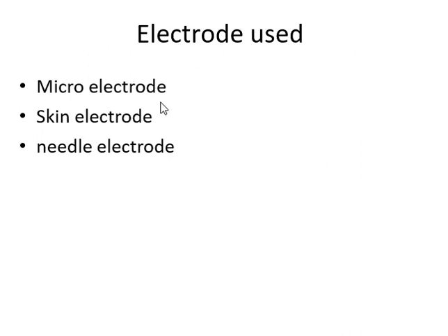And the next one is electrode types. Microelectrode. Microelectrodes are very small electrodes that can be inserted into the plasma membrane without destroying or causing damage to the cell. Microelectrodes are made from inert metals with high Young's modulus such as tungsten, stainless steel, platinum, and iridium oxide.